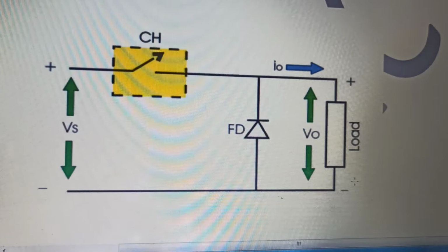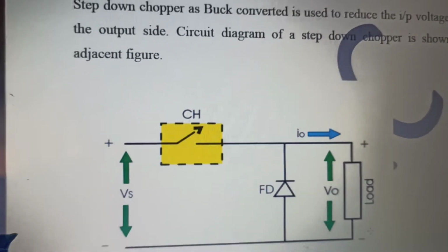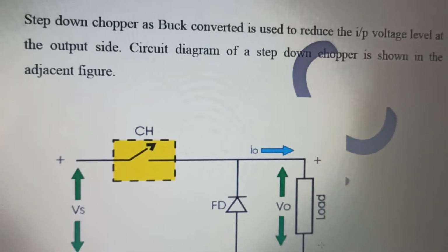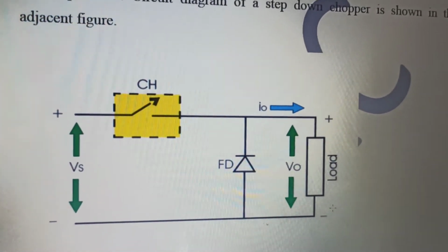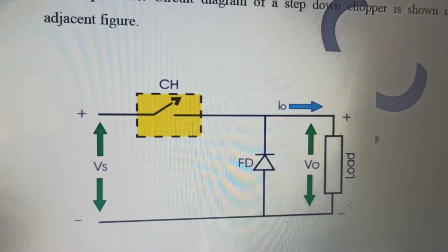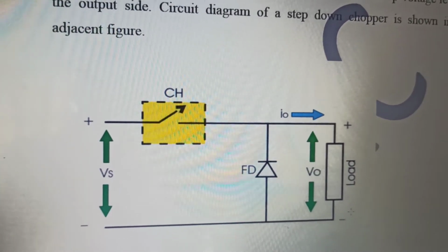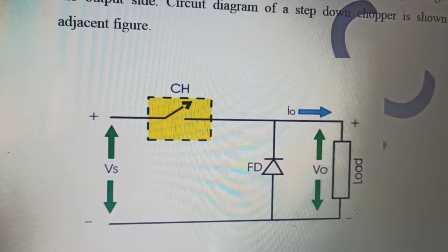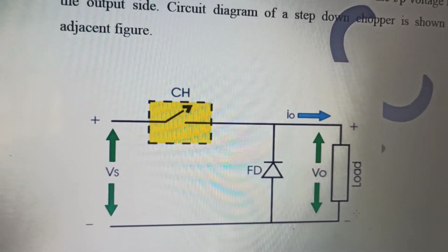Now, again, very good. It's very fine that the role of capacitor becomes clear. What will happen to the current now? For filtering out the ripples in current, for reducing the ripples in current, we will use an inductor. Basically, what is happening is that the inductor will not allow a sudden change in current, so obviously the variation in current will become low. The lower variations will be there.